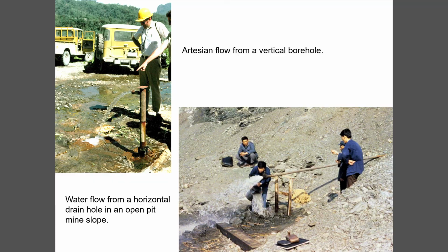They're quite useful if you have a fairly small rock slope where the joints would be clean, you wouldn't have too much material flowing through the structural features, and where you might get good drainage for perhaps 10 or 20 years. But in a slope with a lot of clay or soil present, the drains clog up. Whatever you try to do to protect them, they clog up too quickly.